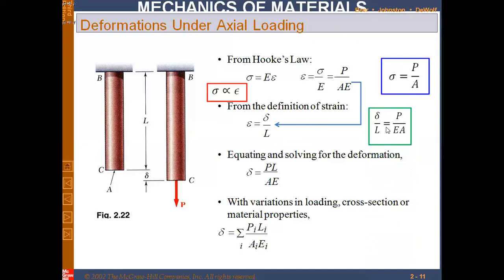Multiplying both sides by L gives the deformation delta, so delta would be equal to PL by EA.